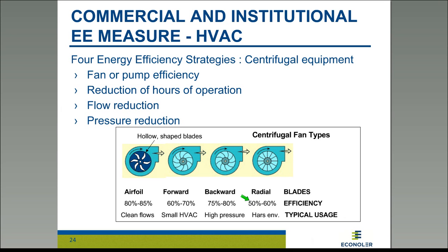Efficiency is around 50% to 60%, meaning that only 50% to 60% of the energy is transformed to pressure and flow. The rest is lost in heat generation because of eddy currents in the flow in the fan. So this one is used mainly for harsh environments.